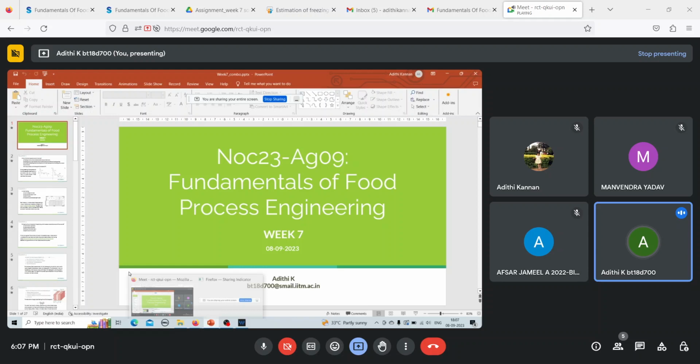And the temperature change is delta T1, and delta H2 is the enthalpy change during the phase transition and the post cooling. That is from B to C and C to D. If you remember, you have a phase transition which is almost a straight line, and then further cooling will result in sensible cooling again. From C to D, you will see a temperature drop. So delta H2 involves the enthalpy change during the phase transition stage and the post cooling stage. Delta T2 is the temperature difference at that stage.